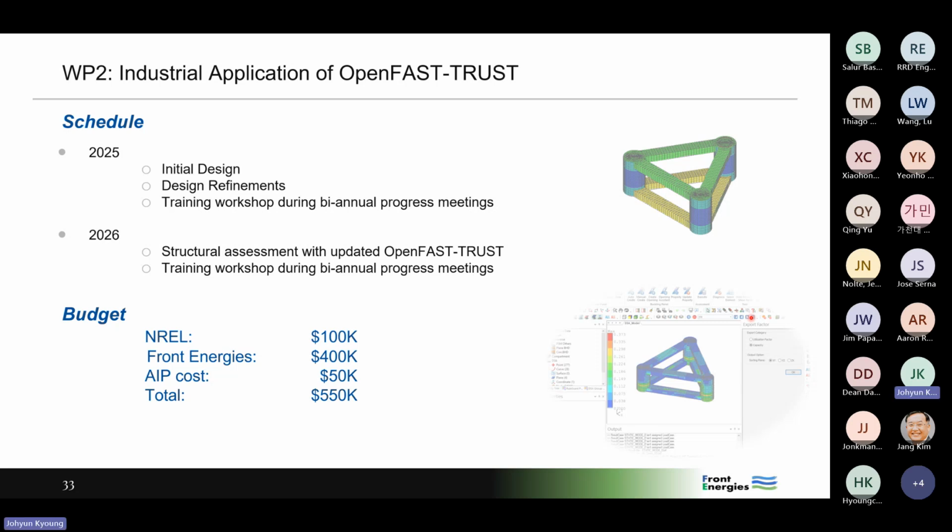We are not trying to make a new design, but more like make a good example for industry people, especially the young and starting companies, who can follow step by step. So we'll try to offer as much as possible, starting from the scantling check, sizing sheet, all those things. This is more like training material, but all the design should at least go through the industry standard procedure, hopefully carrying some AIP too.